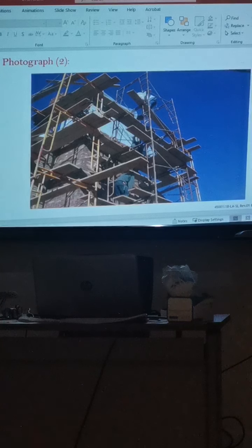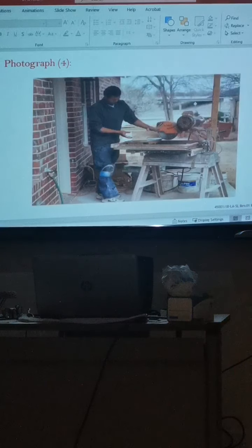Is it clear? Sir, I have one question. Okay, please. During my field inspection, I see my employee is working with the equipment, and the electrical wire is exposed, cut, but he doesn't know, and I know. For some time he doesn't know, then they inform me. Will that be counted in my documentation as a near miss? No, it is operational control. He could touch the exposed wire. I rectified that. That is lack of operational controls. It was an unsafe condition.